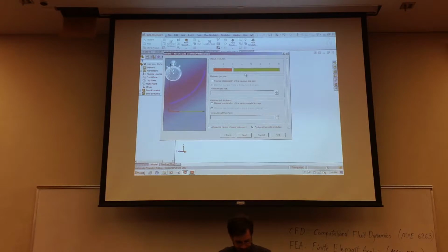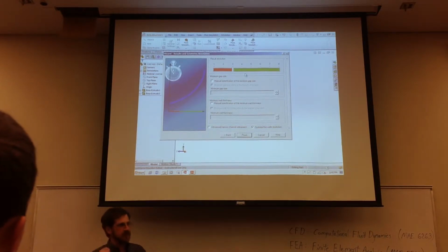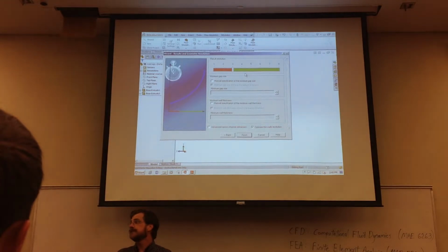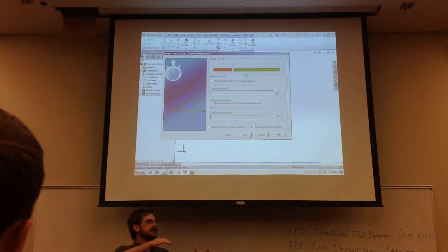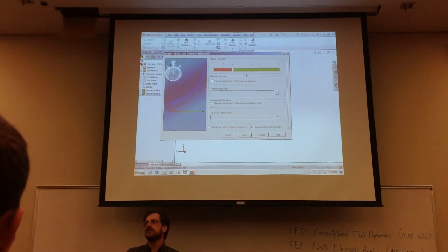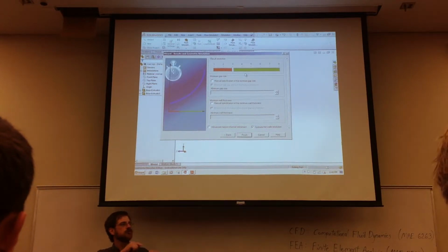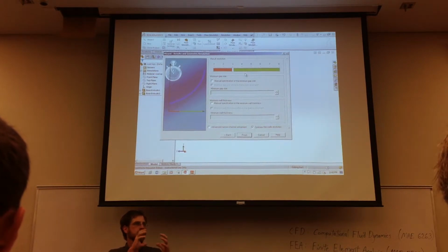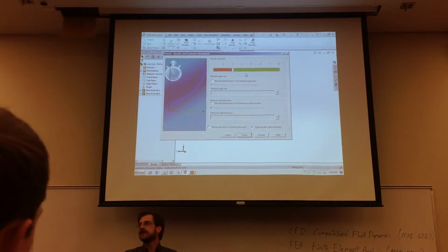So, what SOLIDWORKS is going to do to analyze this situation is take some volume of air surrounding the sign, and discretize it into a grid or a mesh. For example, if we were going to do a CFD analysis on this room, we might take the entire volume of this room and break it up into 1 cubic meter blocks and just fill the room with all these chunks of air. Now, that would give us a result.